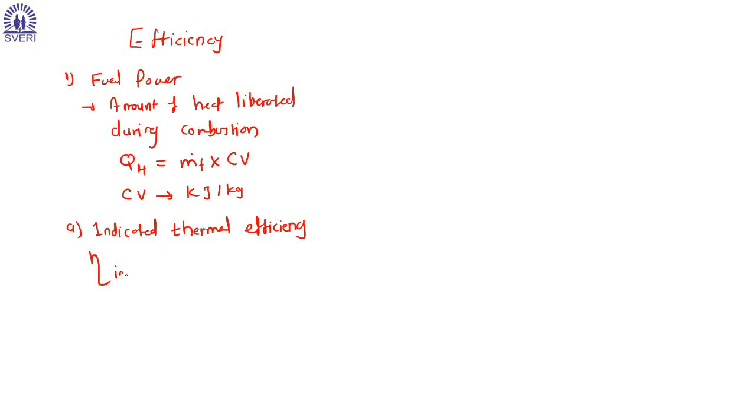Indicated thermal efficiency is the ratio of indicated power to the fuel power, which we give as mass flow rate of fuel into calorific value of the fuel.